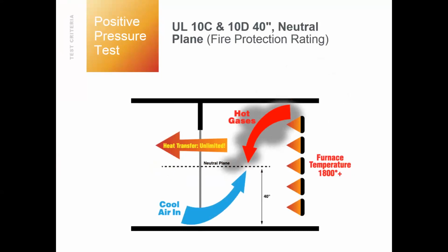And if you look at it, this fabric product in this opening creates this convex and concave nature, essentially giving it a quasi-structural integrity test. But if it passes this portion of the test, this burn portion, it carries whatever hourly rating the fabric product was going to achieve. So 1 hour, 2 hours, 3 hours. It doesn't burn that quarter-size hole that I was discussing through the cool side of that door. It's fine. It passes, no problem at all. And then it obtains that hourly rating.